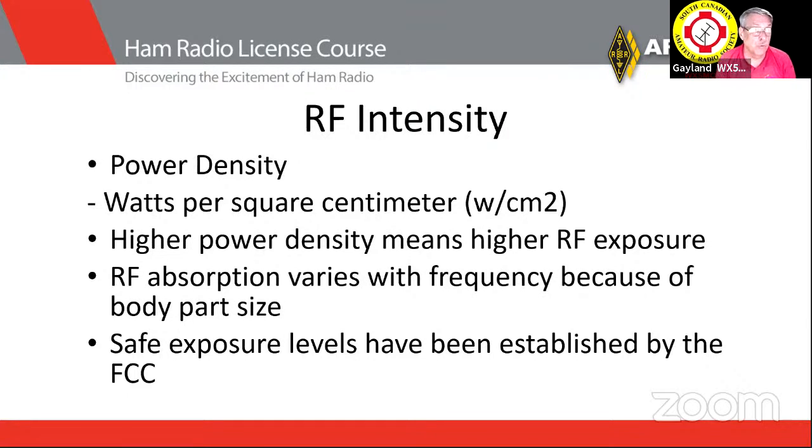What if that antenna is on the ground or near the ground and I have my transmitter hooked up out there trying to adjust some things? Does that change the equation a little bit? Yeah, it does. Let's go back to the handheld. Okay, my power level, I'm about 2 inches. Do I have more exposure at 5 watts or 50 watts? 50. Yeah, that's why these aren't allowed. These are 5 watts or less. Again, depending on your frequency.